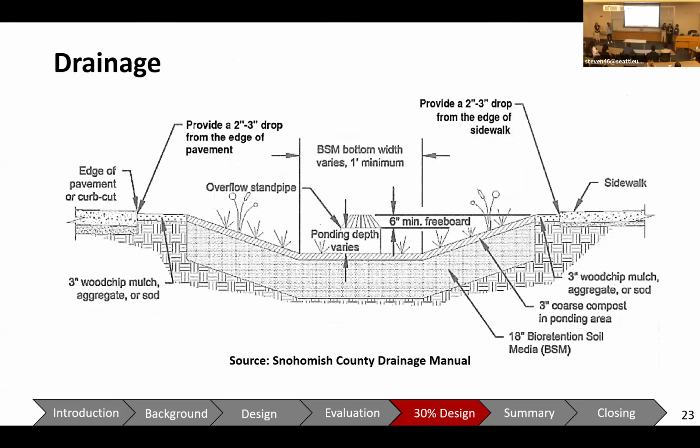There is no drainage facility currently, so in order to fulfill the minimum requirement of the Snohomish County Drainage Manual, we propose to install a bioretention swale that will remove pollutants and decrease runoff. So we followed a requirement from volume 5 of the Drainage Manual, and we modeled the simulation in the Western Washington Hydrology Manual to make sure that the swale will filter 100% of the runoff.